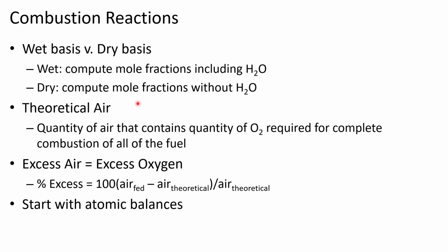Theoretical air really builds upon the description of theoretical amounts that we've talked about in previous problems involving reactors. The theoretical air is the quantity of air that contains the quantity of oxygen that's required for complete combustion of all of the fuel. So theoretical air includes not just the theoretical quantity of oxygen required for complete combustion or complete reaction, but it also includes nitrogen that would come along with it.